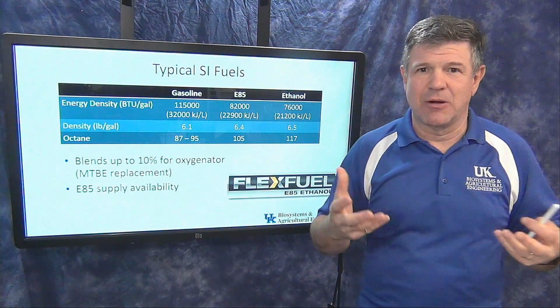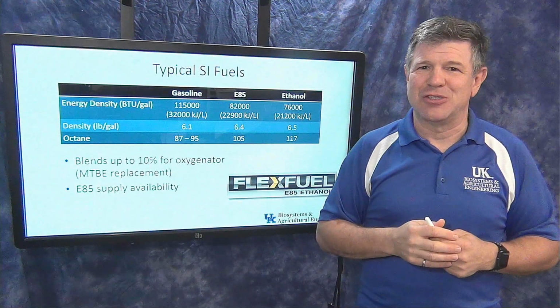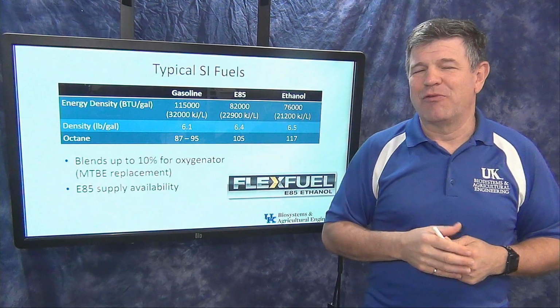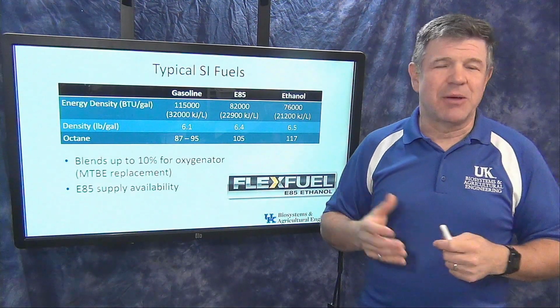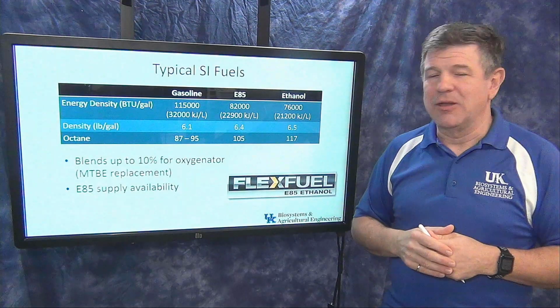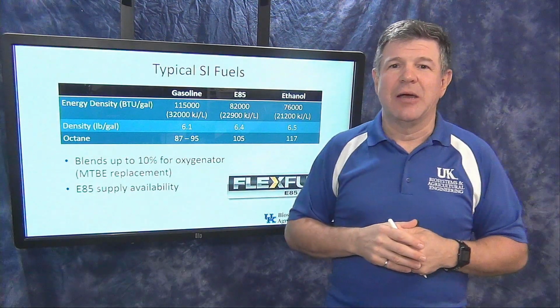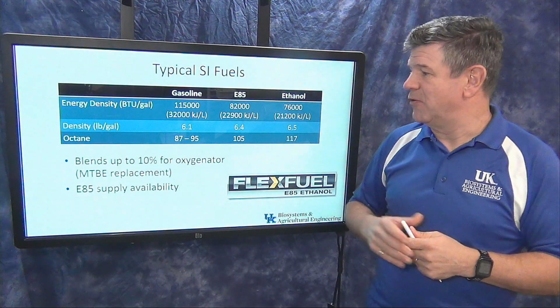I mean, likes in terms of likes it for lunch, so it can actually damage and destroy some of those aluminum or fiberglass type products and storage containers and so forth. And so in some of those applications, we want to make sure we don't have ethanol in it. But most of our fuel, if you just go to a gas pump, you're going to get some ethanol in your fuel.